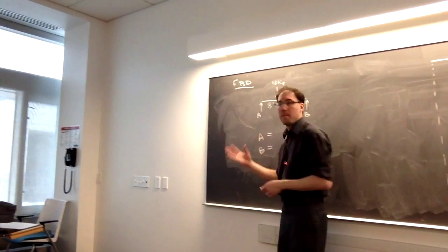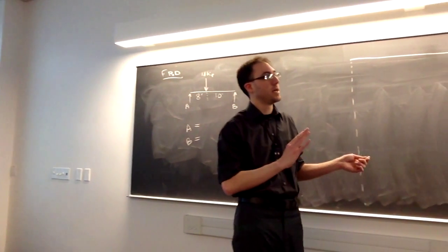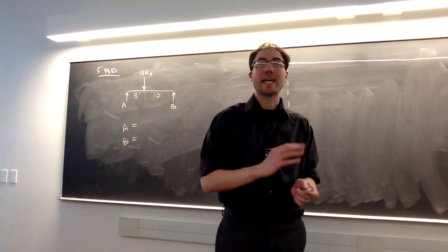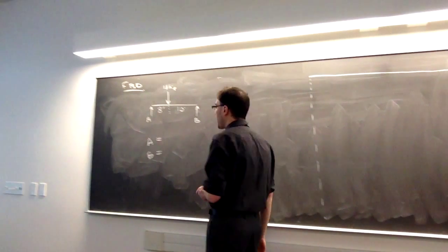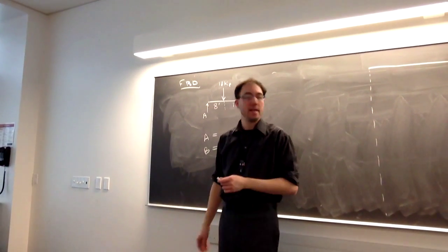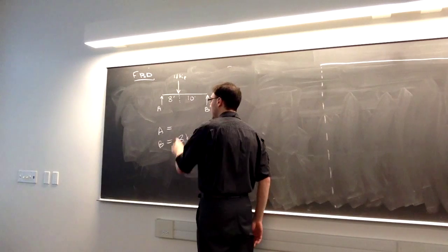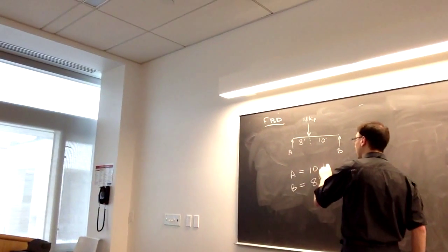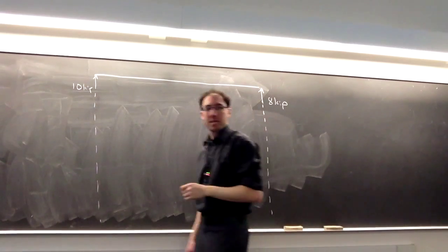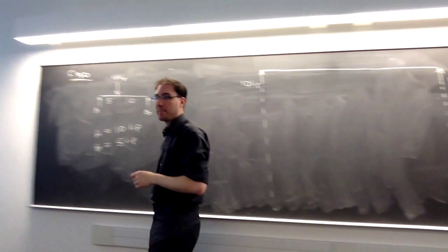From the free body diagram, all we have externally is this linearly increasing distributed load. What do you get for the reactions at A, the pin, and B, the roller? Right, so you get B is 8 and A is 10 kip. So taking this, putting it over to the top of the VM diagram.